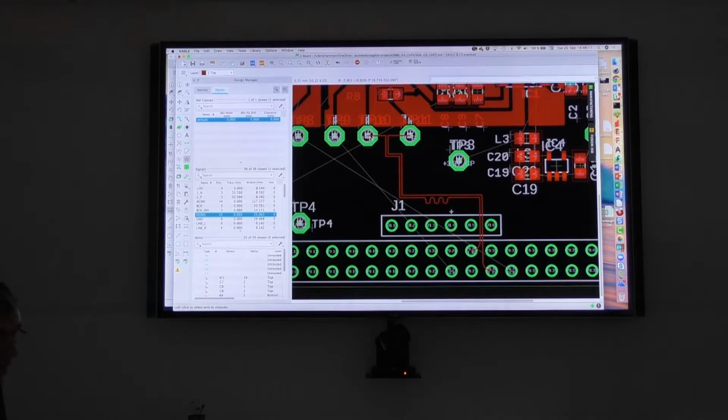Very easy example. Of course, I could also add meanders on different locations. I could also go in there. And, okay, it's not possible because I have 100%, but I could split this as well. And so that's the way how I could do a length balancing in Eagle.